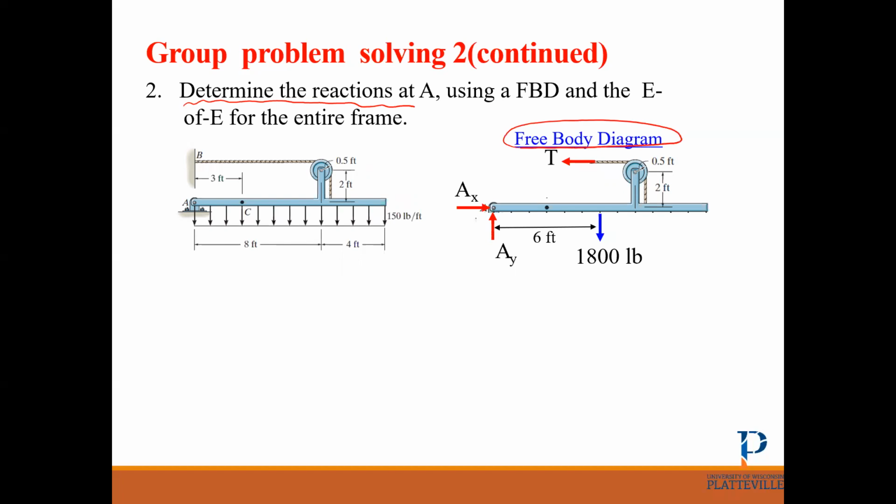Make sure, similar to a truss, when you want to find the reactions, you need to consider the whole structure and then do the cut, because sometimes students do the cut first and then find the reactions, or they see a lot of unknowns. So we have 3 unknowns here and 3 equations of equilibrium. Go ahead and find out what these forces are.